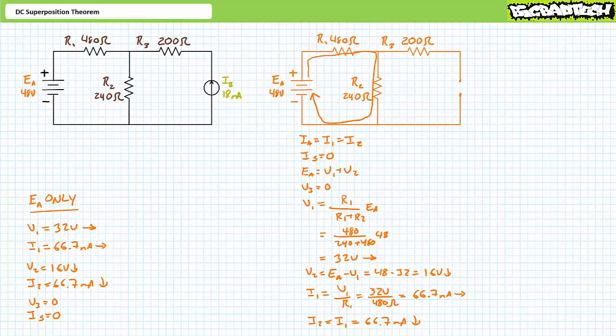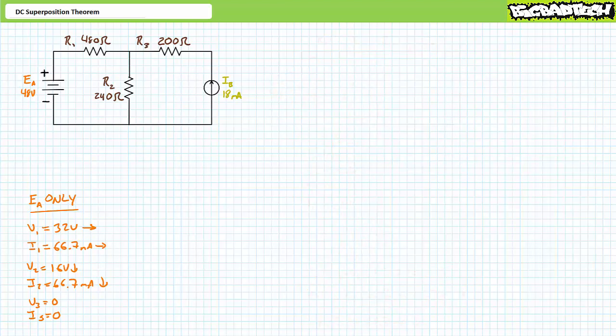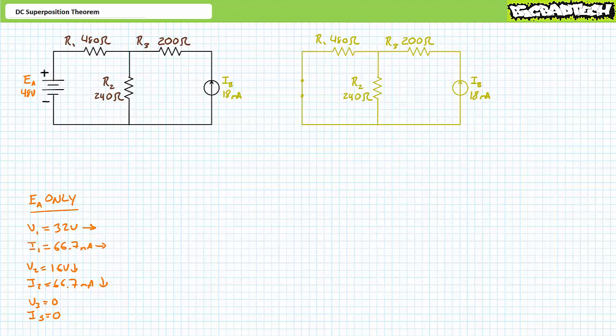The series parallel analysis from the perspective of the voltage source is now complete, and now we can move on to the next step, which necessitates we perform the same analysis for the remaining current source. This means we need to remove the voltage source by replacing it with a short circuit. Note that when we redraw the as-analyzed circuit, including the short, the nature of the circuit is again fundamentally changed.